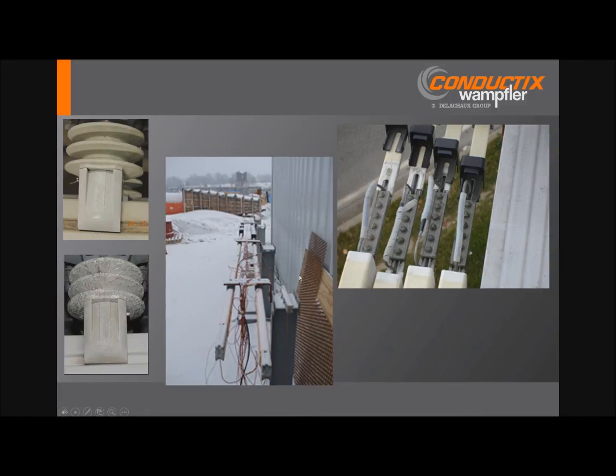Precipitation can be problematic, whether it's rain or snow. Obviously, in very cold environments, it's possible that you may get ice formation on the conductors. Ice is not conductive, so the vehicles won't move. Or if it's intermittent ice, what you'll get is arcing and sparking as those collectors are making and breaking contact across the ice patches, and that could be damaging to the conductors as well.